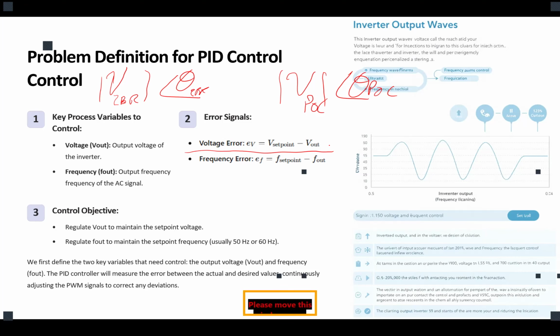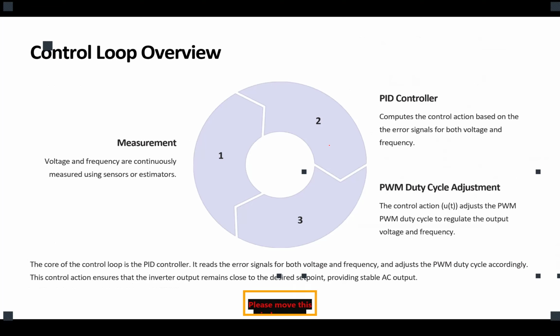Are we good? Did I answer the question? Any other question about the general PID? No? Okay. Now, when we define the situation, the parameters, and the error signal, the way that PID control works is the continuous correction of the error. We are going to see how the PID controller tries to eliminate the error. It calculates the error and sends the actuation signal to eliminate it. That actuation signal affects the PWM, so we could address that error.